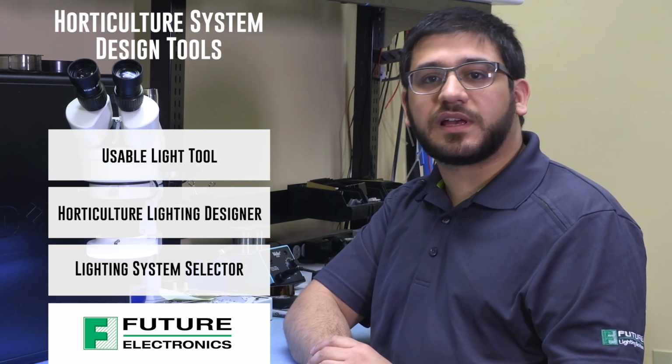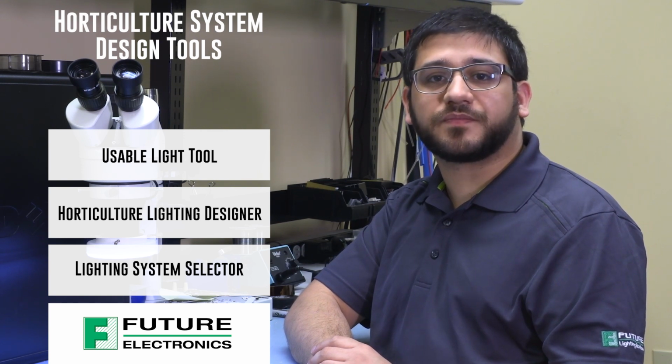The Usable Light Tool, used to determine an LED array's flux, efficacy, and power consumption given an operating current and temperature. And the Lumen Maintenance Projection Tool, which helps evaluate the flux maintenance of LEDs and determine the operating conditions at which a Q90 of at least 36,000 hours can be met.